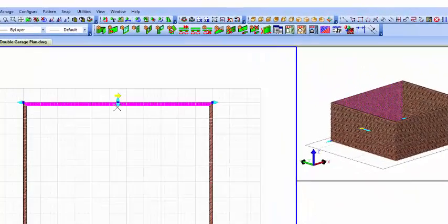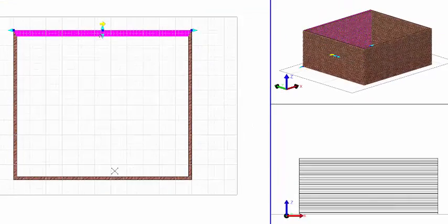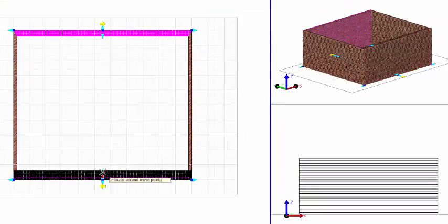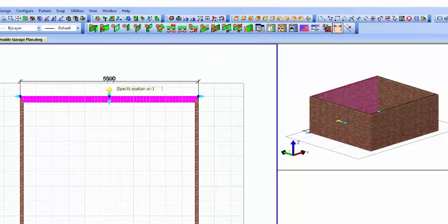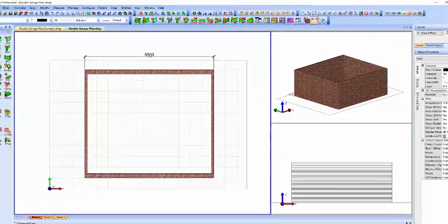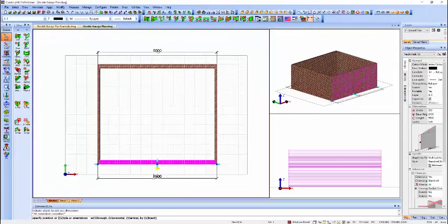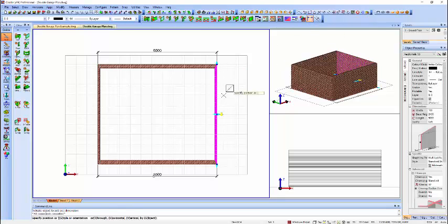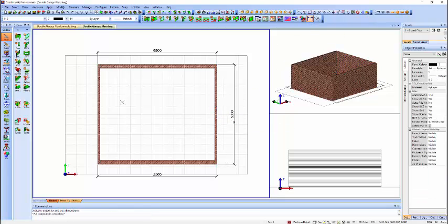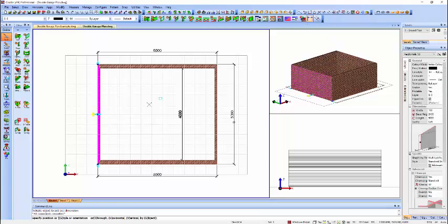We can select our walls and just double the thickness using the grips, so we can pick on those. We can also add dimensions in with the AEC dimensions, so these are automatically generated. We don't need to create these independently. These are based on the walls that we've actually generated within our model. So we'll drop in the AEC dimensions.